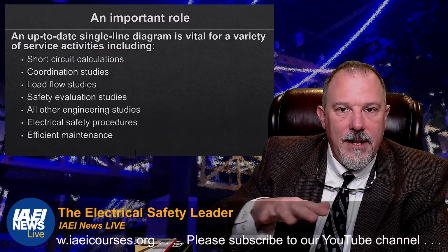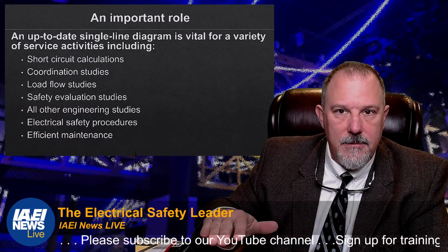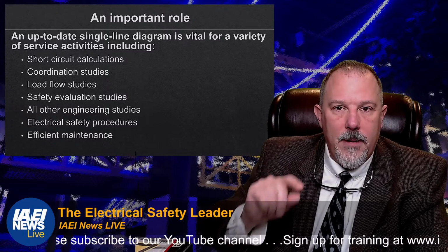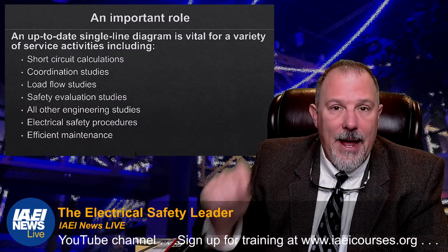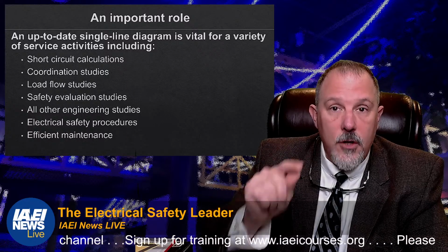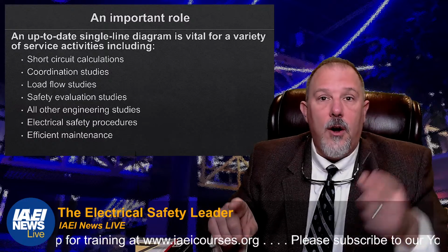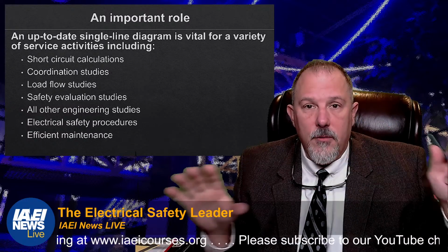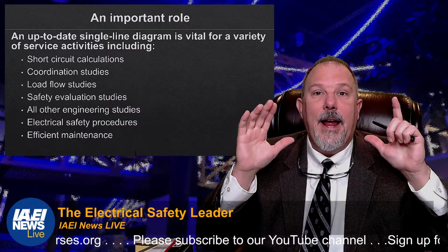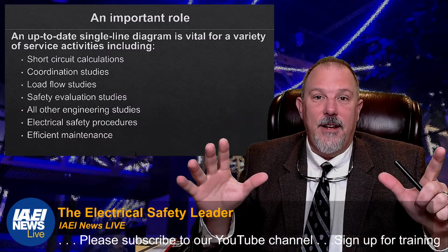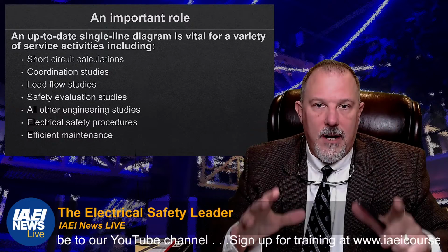And everybody is going to get value out of that single line diagram throughout the entire process. And remember, it's fluid until you get your as-builts. It's fluid until that electrician lands the wires on both sides, has all the raceway in place, has all the equipment on the wall, and they gaze on perfection and walk away. It's fluid until the job is done.